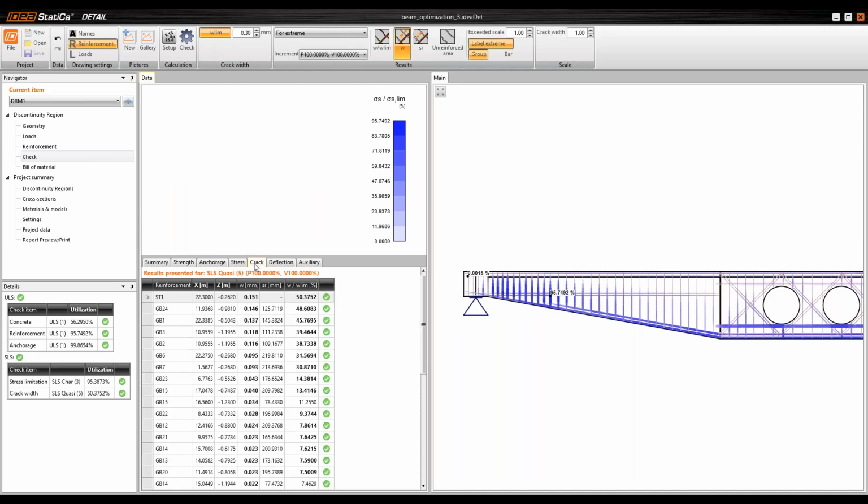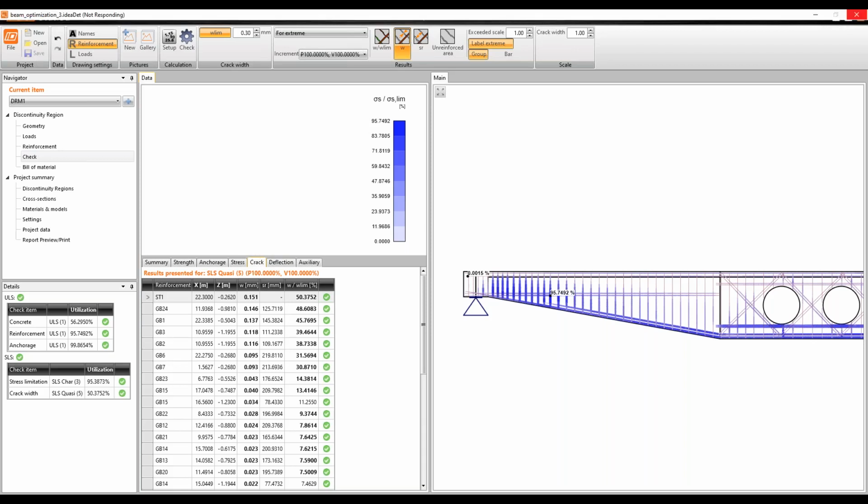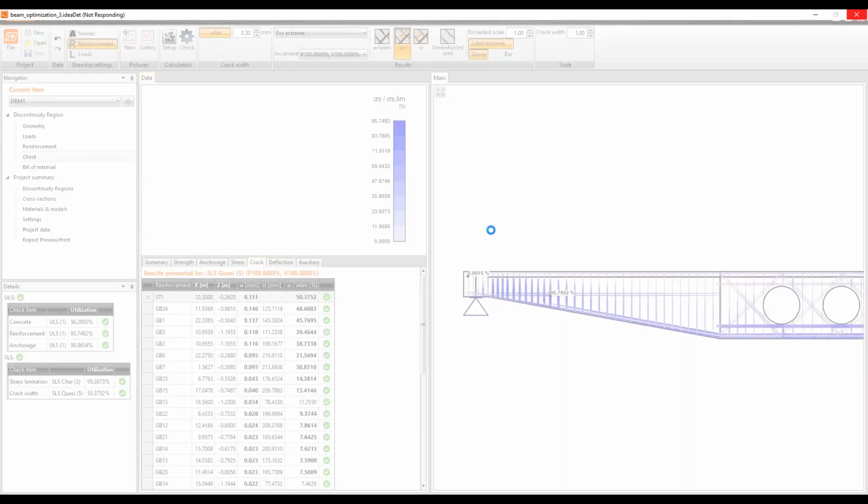I want to show you the crack width check also, and the other serviceability limit state checks, because those are the checks that you cannot get from Strut-and-Tie methods. Using the compatible stress field design, we are able to check where the cracks are forming, their widths, and also we can check the deflection of the structure, which are really important for the engineers in general.